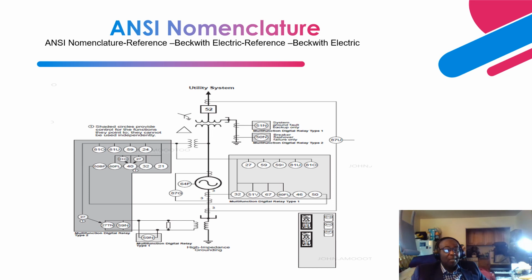So the next element is 87G. This is the differential protection. This is the main protection system for the generator, right? So basically, you have CTs at the terminal of the generator and CTs at the neutral of the generator. So basically, it's measuring the difference in current.